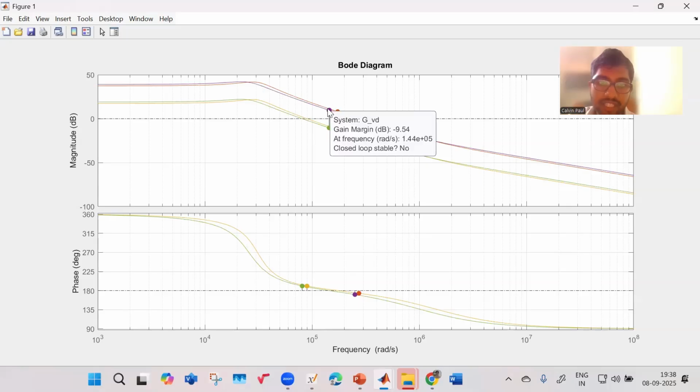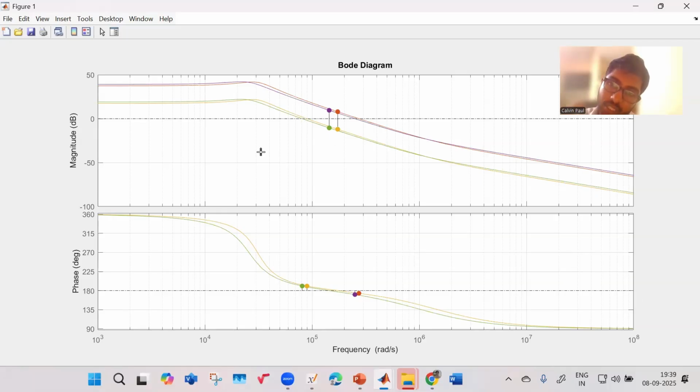As I change my input voltage, again the response changes. In this small part, it is getting shifted. So that's why a change in input voltage can affect where it is crossing. But it is not exactly clear how much your loop will change if you change input voltage by this much.